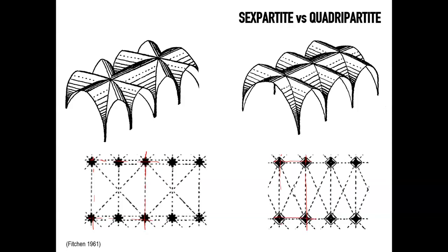Yes, much has been said, there's more verticality, it enhances the verticality of the space, etc. But the reality is that if you have a vault with a square bay, like what the sexpartite does, yes, because the sexpartite has some piers in the middle, but the thrust that comes here is mostly along these four piers. And what happens here is the component of this load from the vaults and from the diagonal ribs, which are the ones that pick up most of the loads, and they are the first ones that are built, by the way.